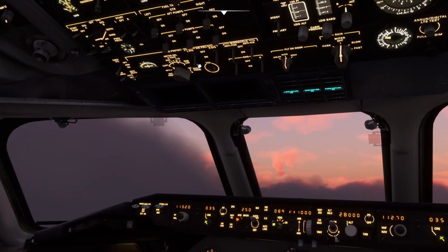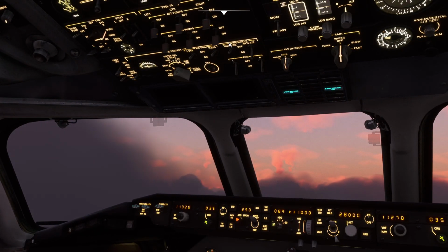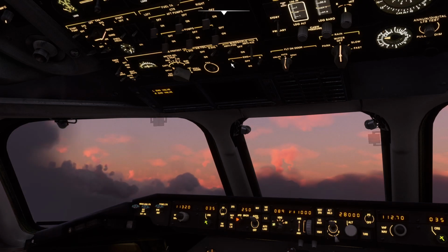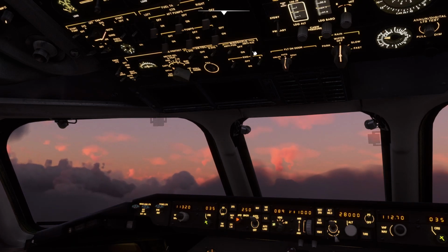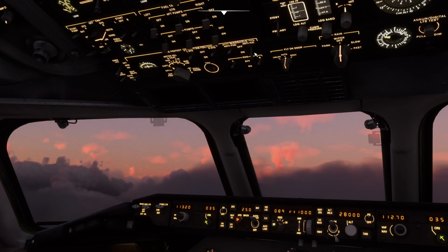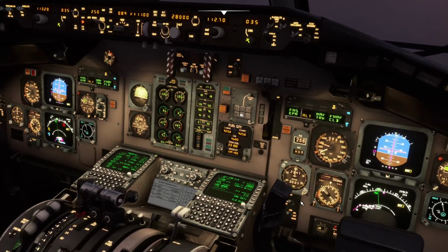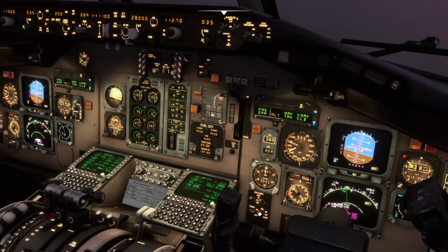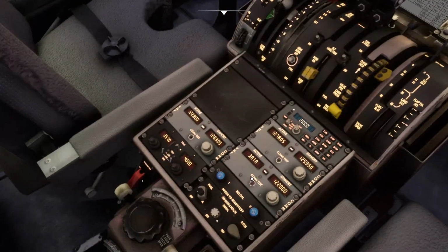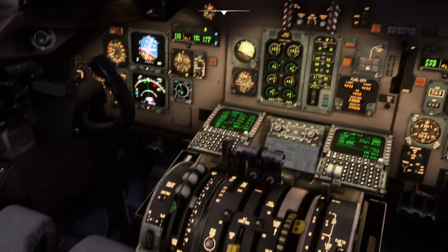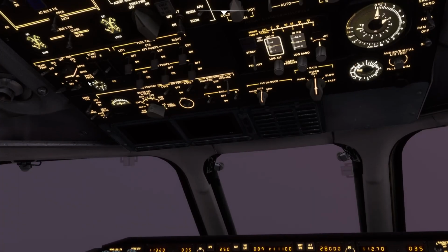So by doing that, we'll just flick off the airfoil anti-ice, the windshield anti-fog, and the engine anti-ice. Those are the anti-ice systems. The windshield anti-ice is like a window heat, so it stays on all the time. And we can, in that case, turn off the trans and aux pumps and close the pneumatic crossfeed valves, as well as turning off continuous ignition.